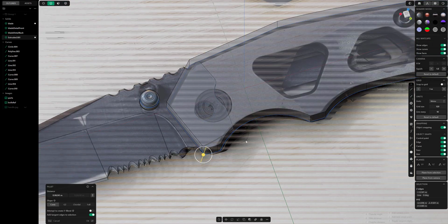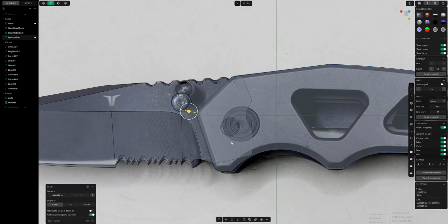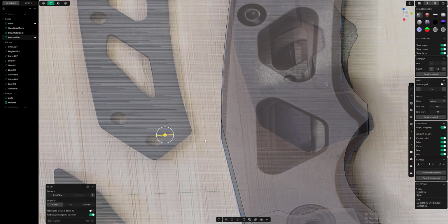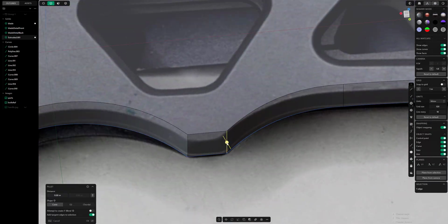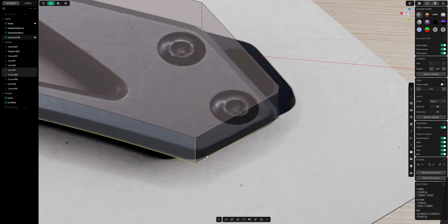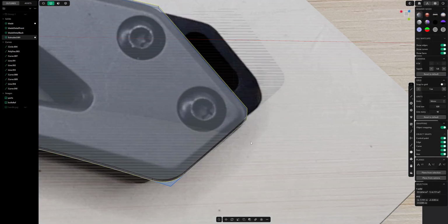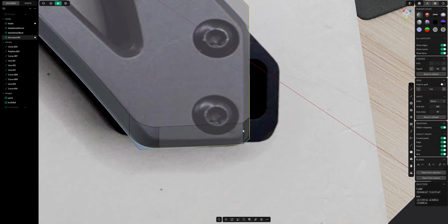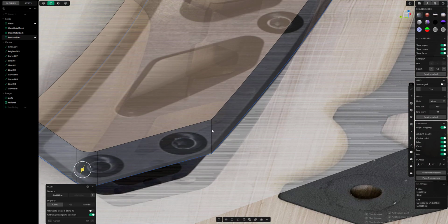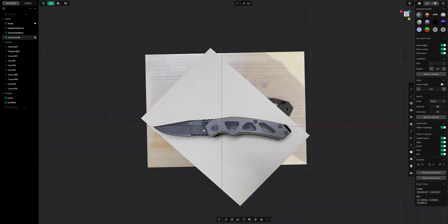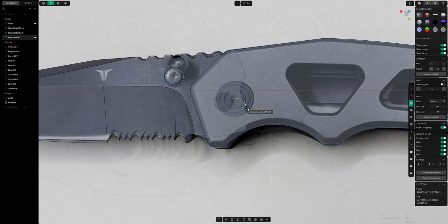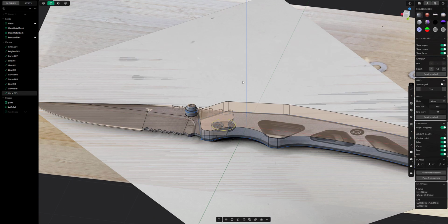And now we can go ahead and soften some of these transitional pieces with chamfers. So you can do this by control point too. You can also chamfer fillet control points. I tend to see it a little bit better when there's actually some volume. And here we can just delete that. We should be able to dissolve that face now, yeah. And then let's go ahead and just fix that guy up. Really simple. It looks good already. Let's go ahead and punch a hole to where the pivot goes. So just drop in a circle.